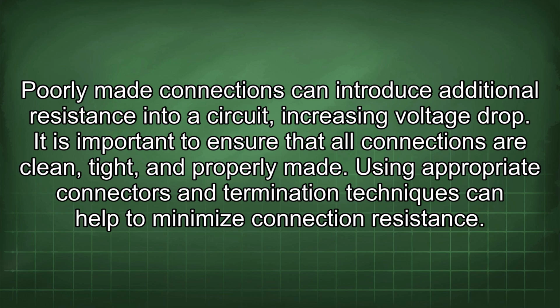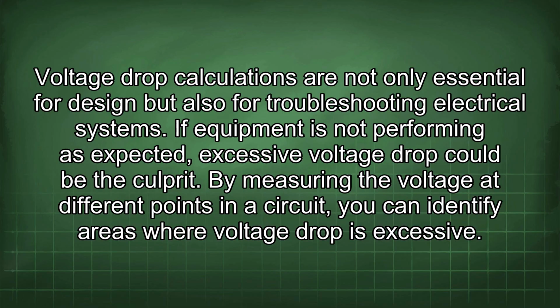It is important to ensure that all connections are clean, tight, and properly made. Using appropriate connectors and termination techniques can help to minimize connection resistance. Voltage drop calculations are not only essential for design but also for troubleshooting electrical systems. If equipment is not performing as expected, excessive voltage drop could be the culprit. By measuring the voltage at different points in a circuit, you can identify areas where voltage drop is excessive.